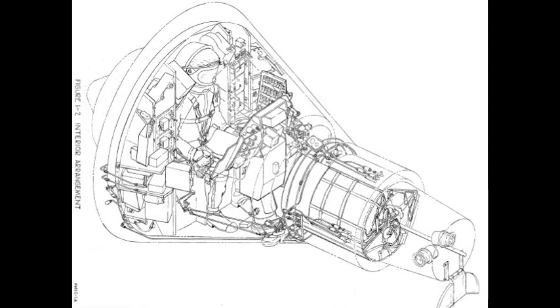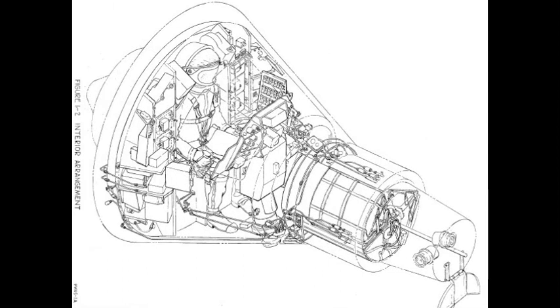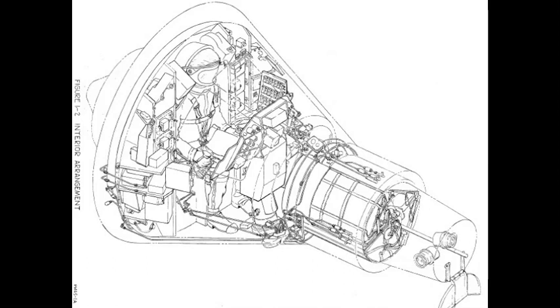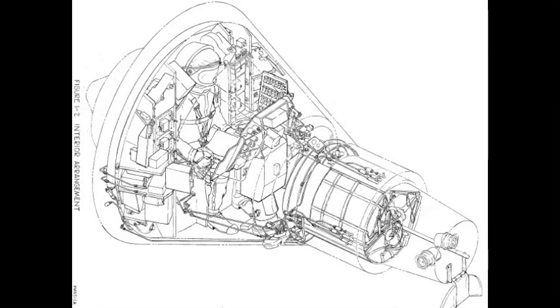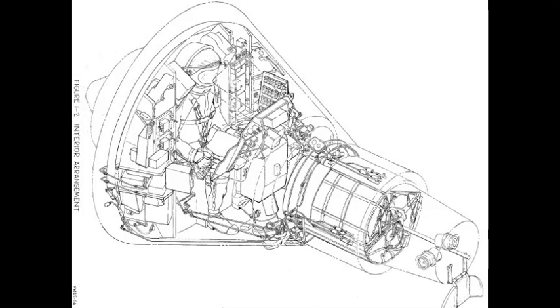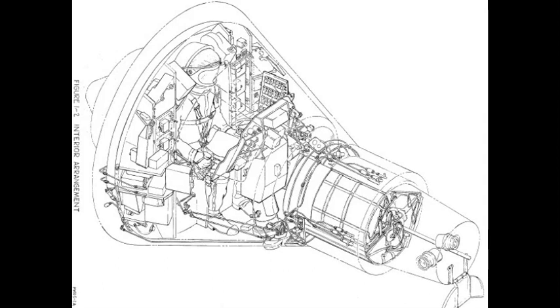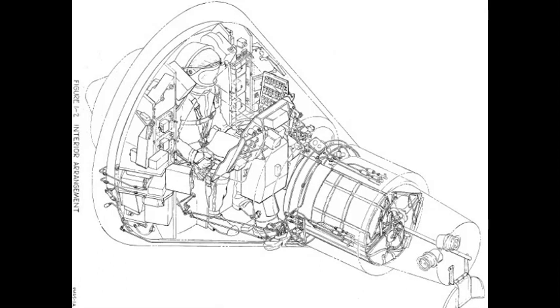2.4. The forebody area between the large pressure bulkhead and the heat shield is vented to atmosphere through a series of vents located around the periphery of the capsule forebody, adjacent to the forebody and afterbody junction. Located in the forebody area are 2 toroidal-shaped hydrogen peroxide tanks, reaction control valves, and nozzles. A landing impact bag is also stored in the capsule forebody area.